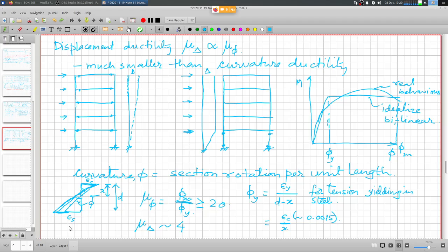So total displacement ductility is defined as maximum displacement divided by the yield displacement. Now this is the maximum displacement, and I define the yield displacement accordingly. If I define this load displacement curve similarly, then it will be like, okay, let me draw this separate figure.